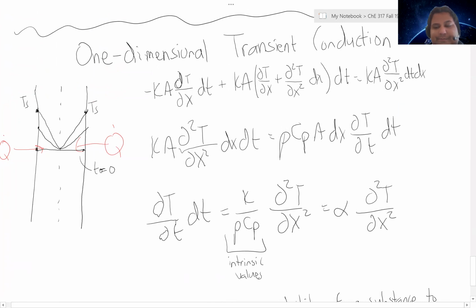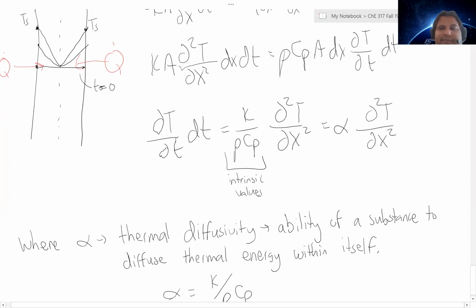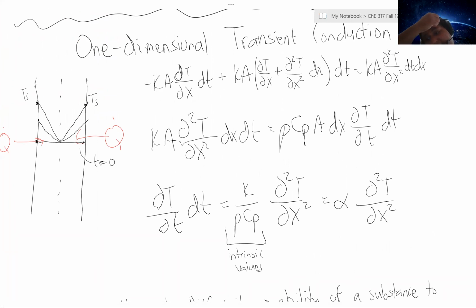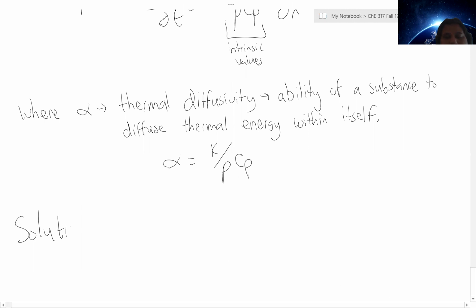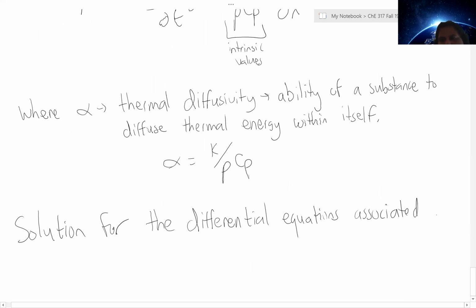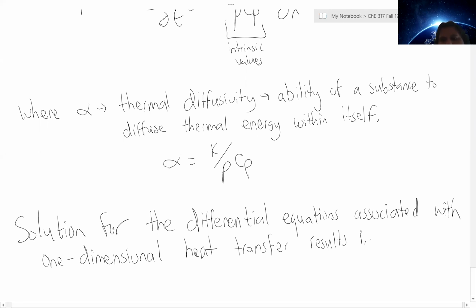And so with this in mind, what we find is in solving these differential equations for a one-dimensional system, it can be done, but the solution for the differential equations associated with one-dimensional heat transfer results in what's known as a series solution.